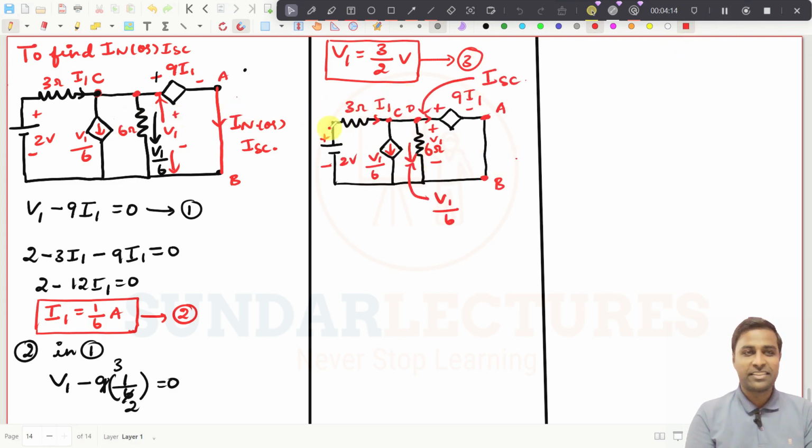See, I have taken the circuit again to explain deep into this particular circuit. Now what I need to do is find this IAC. I have written this IAC here in this place. Both are the same, right? Because this is the completed loop. Whatever the current IAC is here, that will be here. So now you apply KCL at node C.